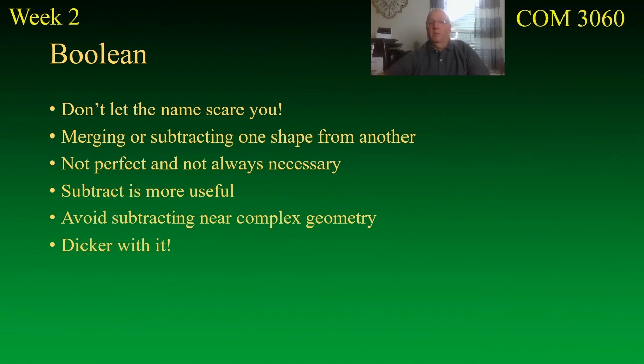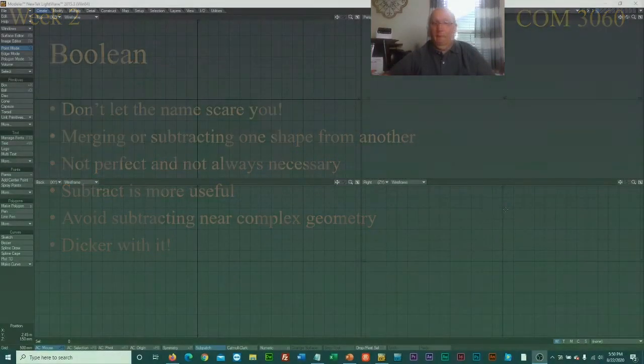Because what's happening is some plane that has that surface can no longer be supported. It becomes impossible. Sometimes a point has moved to some degree. So if you move the point back or merge it with another point, suddenly the problem's solved. But I find that rather than hunting that down, which can take a long time, just undo what you did, move the thing ever so slightly and try it again, see if it works.